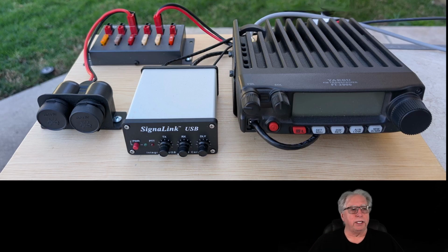Verify that the signal link is on. It's got a green light. Verify the radio is on. Verify the radio is on the right frequency. You don't know how many times you walk into an EOC and somebody has changed the frequency or bumped up against it or whatever, and it's not on the right frequency. So verify that. And you should know what your frequencies are. At least if they're not written down in your EOC, write them down someplace where they're easily referenced, okay?